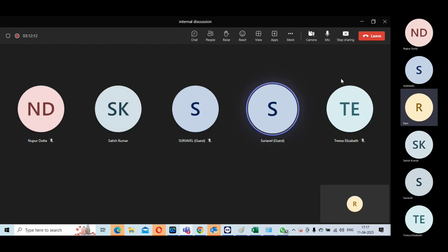The difference is this. In both cases it is treated as a false path, in the sense that there is no connection between the clocks. But if you set it as a false path, whatever crosstalk happens between this clock and that one will not be reflected. That is not true in reality. If there's crosstalk, this transition should impact the other clock. In asynchronous, the crosstalk will have an effect. That's the physics.